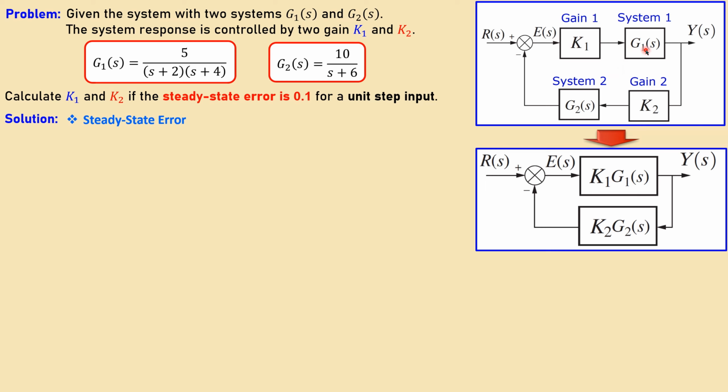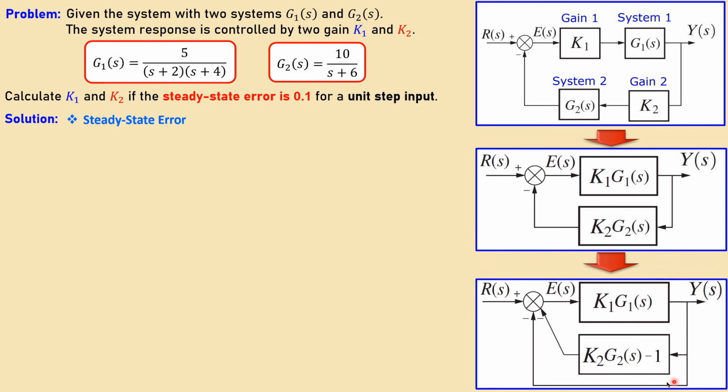So I just first merge these two systems and also these two systems. You can see that here. So what might make one block, and then add here actually -1, and then I add another unity gain feedback here, such that we have that unity gain feedback. That's already also discussed in previous videos about steady state error, when we go from a non-unity gain feedback to a unity gain feedback. That's actually the step from this to that.